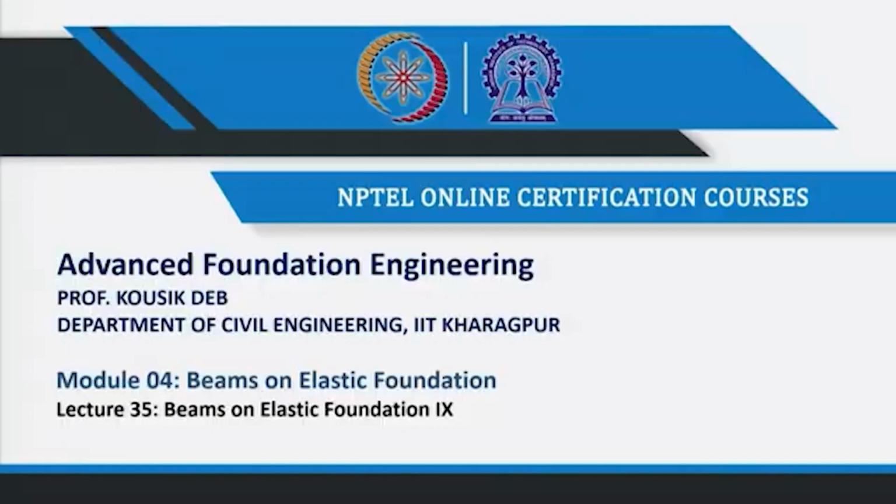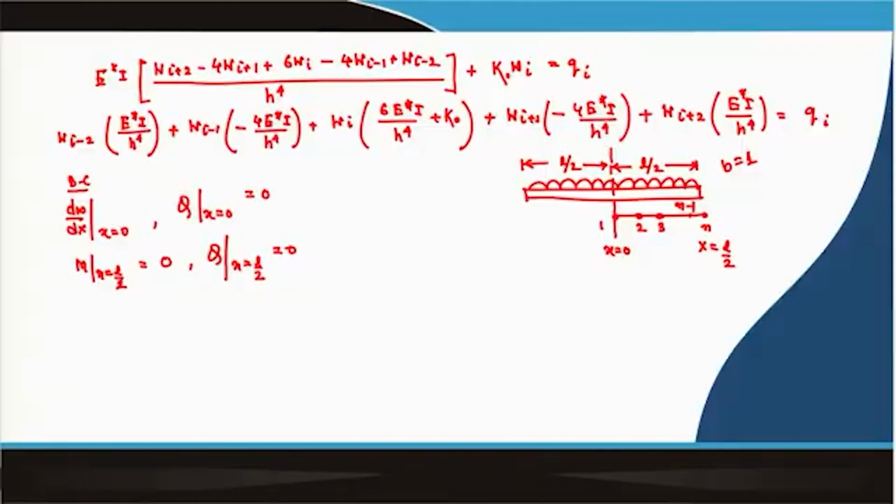So, last class I discussed how we can express this beam equation in finite difference form, and I was discussing the case when the beam is resting on a Winkler spring and then how to use the boundary conditions. So, this was the expression. These expressions, which are expressed in central difference scheme, we have to apply at all the nodes.